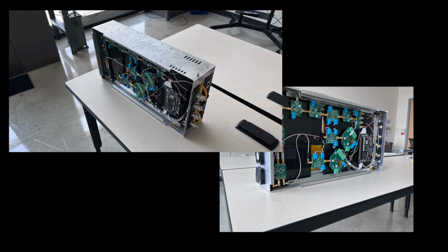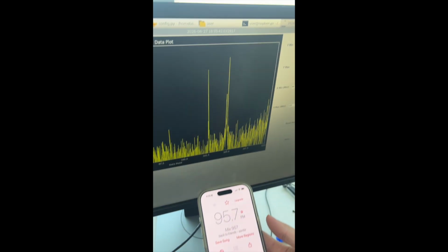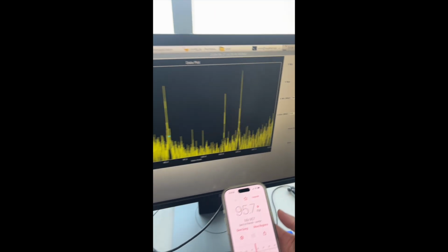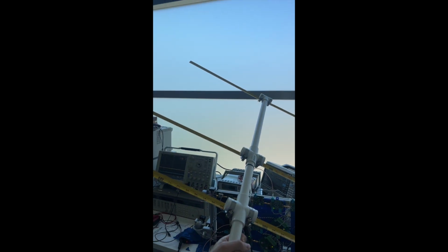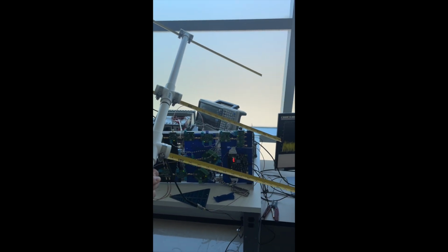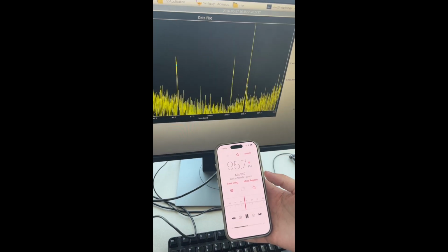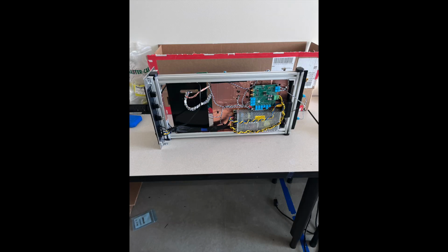The electrical design choices are inseparable from the RF design choices of the project. This project makes use of 9 custom PCBs that all require unique considerations from an electrical design standpoint. RF devices are highly sensitive to noise and interference, so a great deal of care was taken to isolate the RF and digital electronic chains. Our power distribution consists of a 5 and 12 volt AC to DC power supply, along with a custom power board that conditions and distributes voltages across our system.